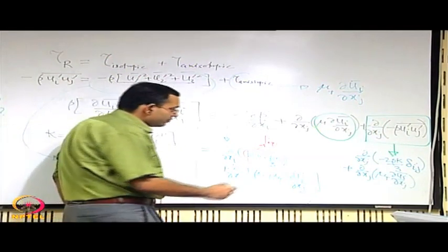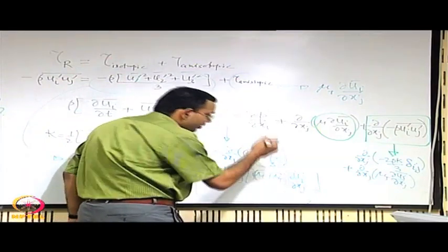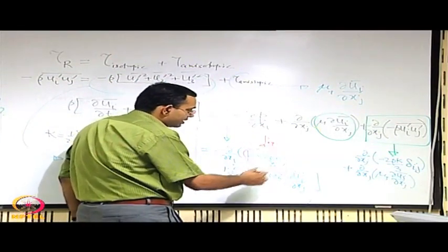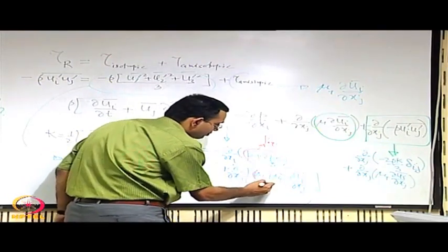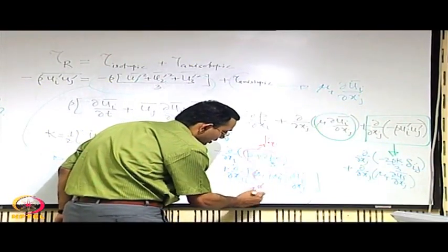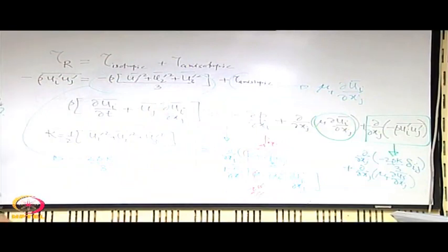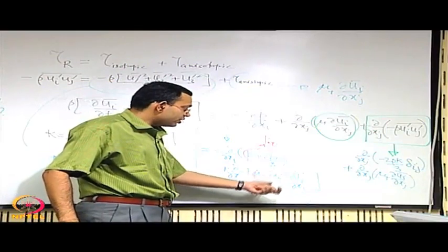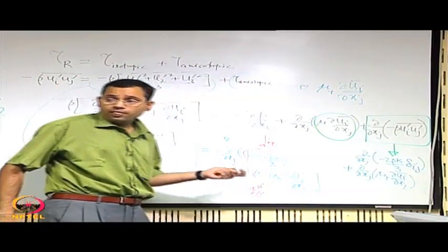The other important observation is that the mu in the original Navier Stokes equation is replaced by some equivalent mu, which is mu plus mu t, or you may call it mu effective, and this mu t, which is known as the turbulent viscosity, is contributing to this mu effective.